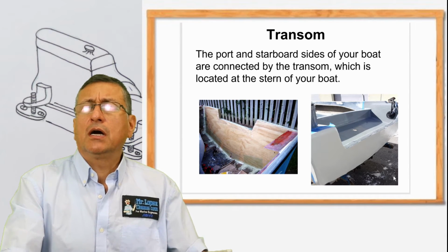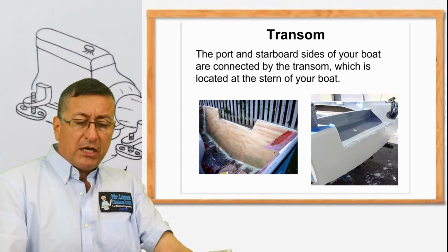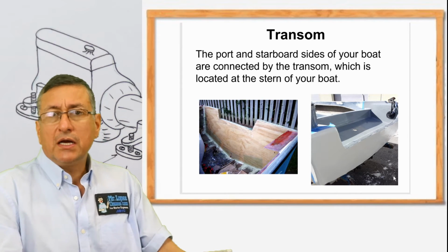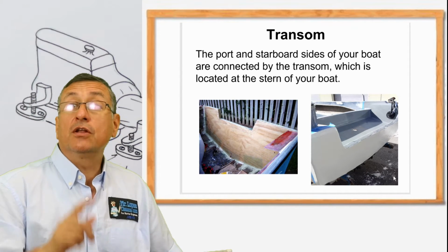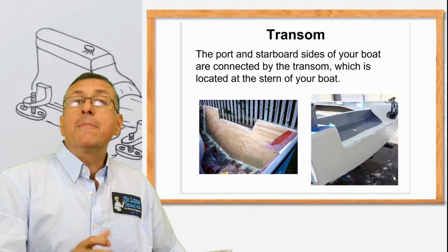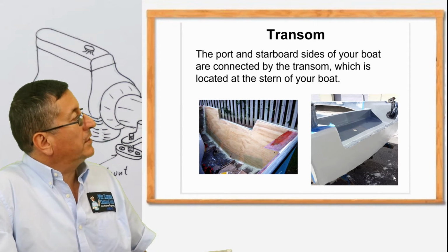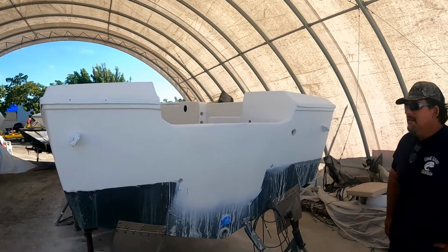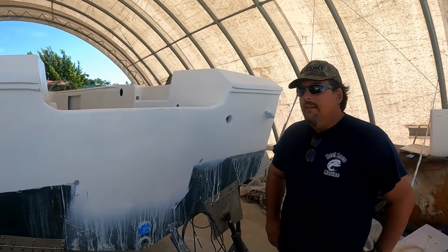For example, this type of transom can be closed completely to convert the boat into another type of boat. We have a great example in the marina of Mr. Rodriguez. Originally it was a half transom, and the transom was closed and reinforced in order to install a big bracket for an external outboard. This is the process.